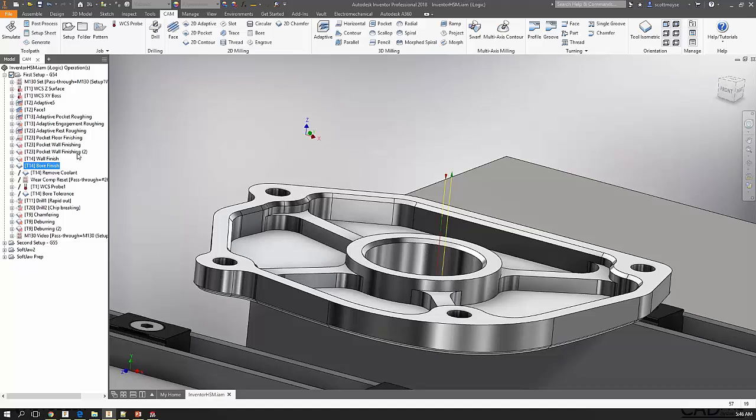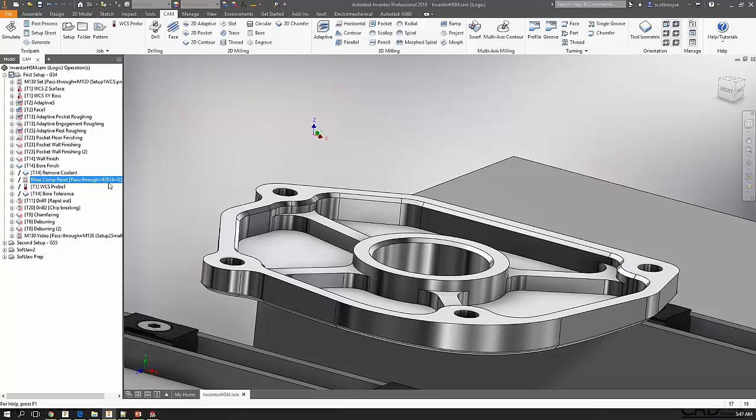So you need to make sure that you clear it out and reset it to 0 in that case, and that's the safest approach to take anyway. I'm not too sure about on the FANUC controls, but on the Haas controls you can reset the wear compensation offset using parameter 26, and then the last 2 digits is the tool number, and then make it equal to 0.